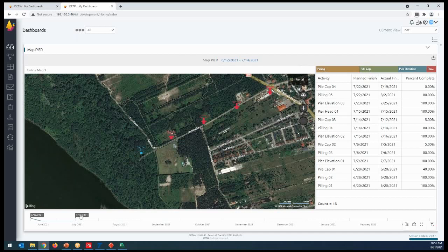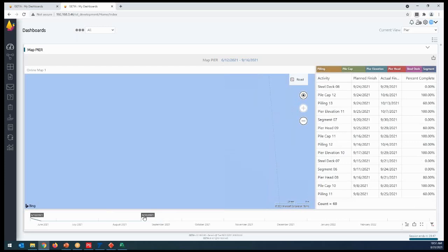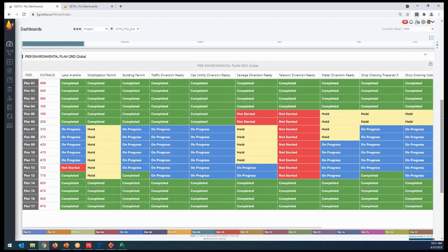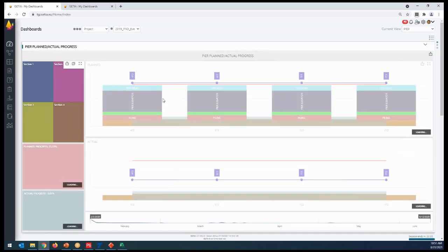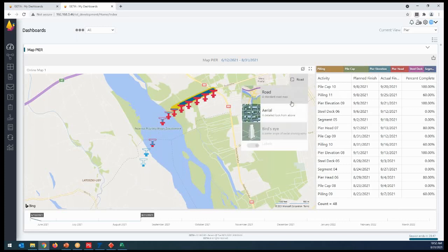If you go to a date of, let's say, September, the system will provide, for example, any specific date. I have decking work start. Yellow is showing baseline, blue is showing actual. Here I can have a planned versus actual comparison as well. I can get a report in graphical view, which is here, like that. Or I can get the map view like this.